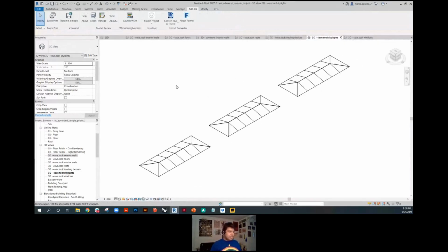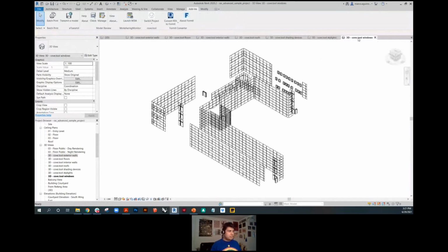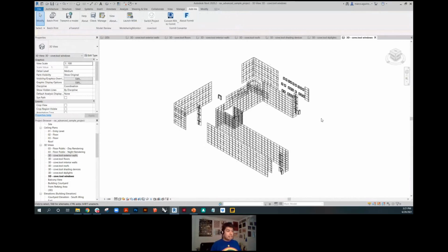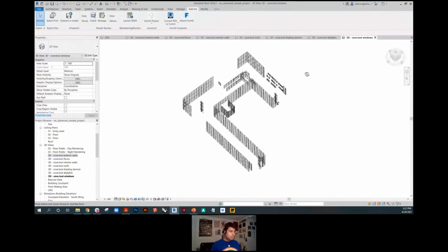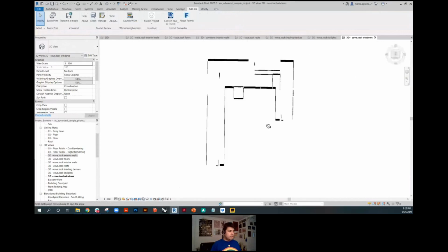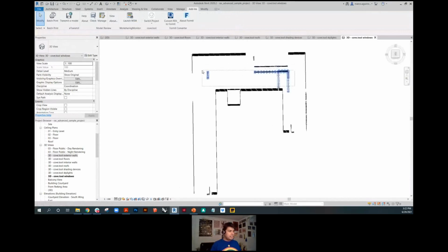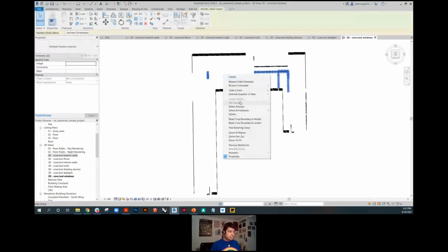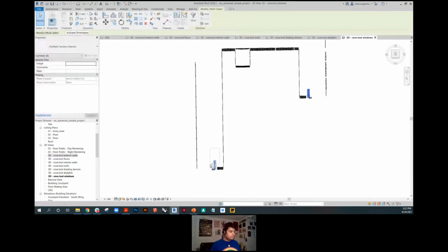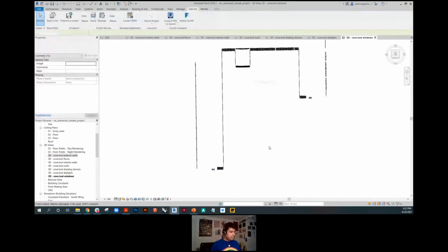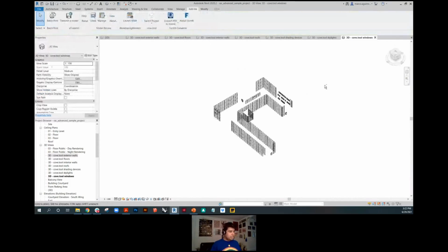For skylights, you've got general skylight objects, nothing I have to clean up here. And also for the optional layers, which are interior walls, shading devices, and skylights, if you don't have geometry, there's nothing you need to create. In order to export, you can just skip those layers and leave them empty. So for windows, again, I just want geometry on the envelope. So I'm going to hide these interior glazed partitions and doors, so I just have the envelope exported. That cleans up all of our 3D views.